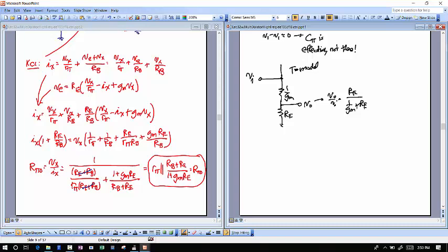That's the comfort I want you to get to with the transistor. It's more complicated. It's got 3 terminals. You've got different gains across it, different resistors, but there's not really that many equations to memorize, I think. All right, so maybe my 6 is a little less than it really is, but it's a little amoebic there, because there's Miller effect and all. So I'm sticking with my 6 equations. Okay, that's really all you really need to know. All right, so let's continue with this. So I've derived that now, and so now I can go ahead and write the total expression for omega h.